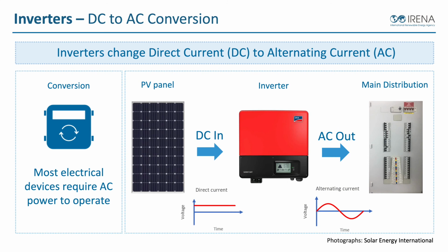Now, the other major component in any solar electric system is what we call the inverter. The inverter, as its basic, simple function, does DC to AC conversion. That's what an inverter does. We do DC to AC conversion because PV panels produce DC, similar to a battery type of system. And then we usually use AC in most of our electrical situations, whether that's our home, our business, industry, running motors, whatever it happens to be. So we really live in an AC world, and most of the devices we use are AC. So the inverter is a device to convert DC into AC.